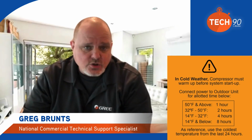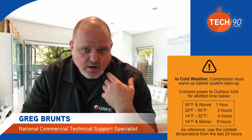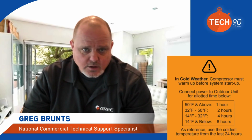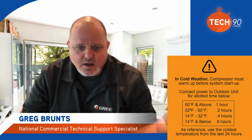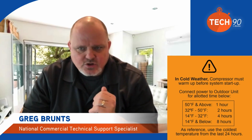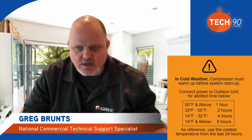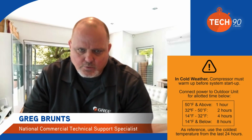That also applies to service. Whether you've got a MultiPRO unit, whether you've got a commercial 3-phase GREE system, whether it be a heat pump or heat recovery, let's say it's got an error code on it. Maybe you've got to get a board for it. Maybe it's just a compressor drive board, but the main board's fine. Do not leave that machine powered off while you're waiting on the part. Leave the power on so that crankcase heater stays warm the entire time that thing is sitting there until you come back with the appropriate part.